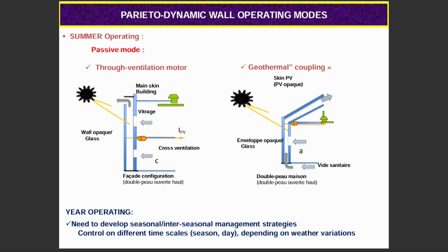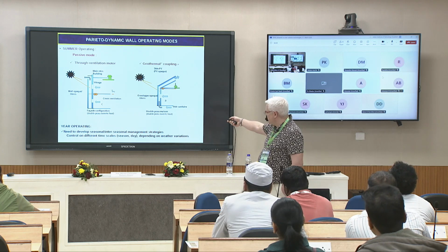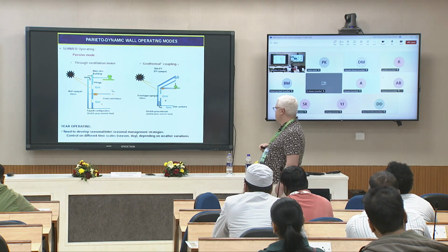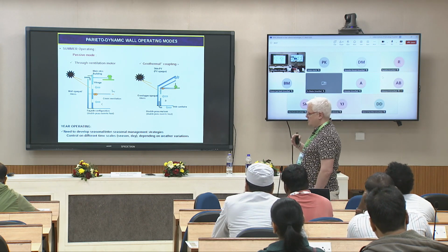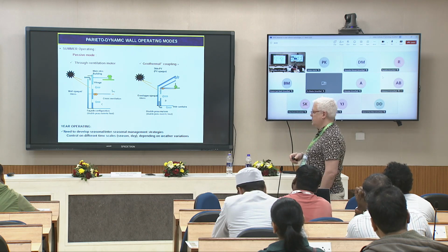You can also combine, it was a historical building that has been refurbished that I showed to you, with a path of air going underground where the air is cooler. So it could be a Canadian well or so. Finally, you are decreasing the temperature of the air because there is a path underground before going in the envelope or in the building. But so it's to use it as a natural ventilation system,